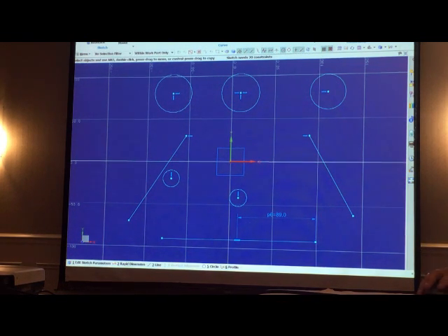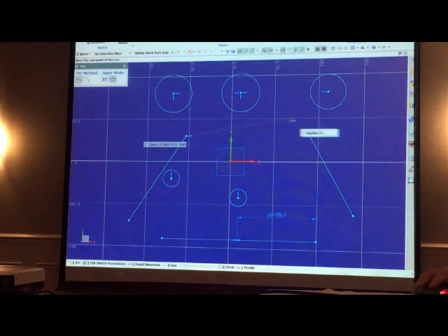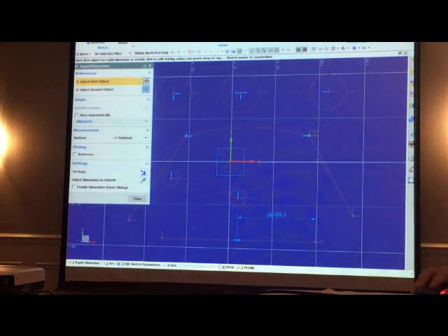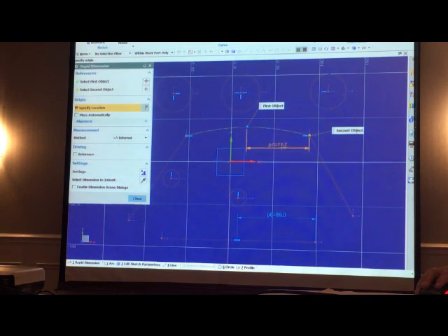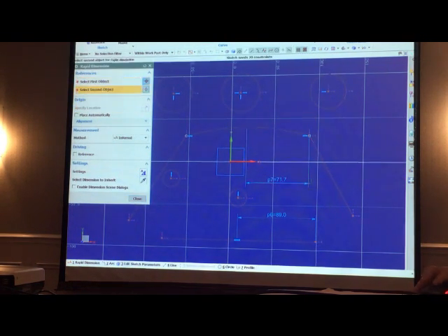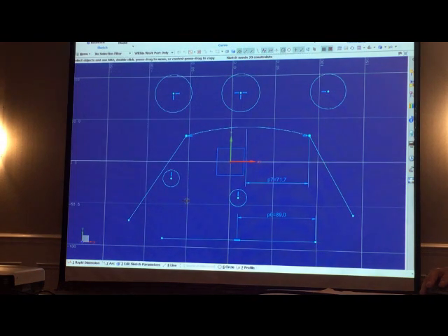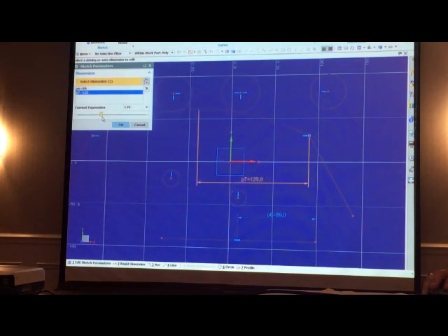And it isn't limited just to lines. Let me put an arc between, let's say, here. And now I'm going to come in here and I'm going to put a dimension from there to there. So I can put a midpoint of an arc too. It's just the midpoint, not the center. See, now when I go to move that one, it actually changes the size of the arc because I'm moving half the arc and it updates the rest of it.